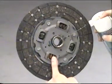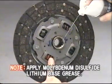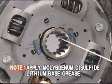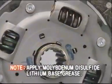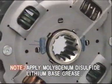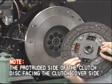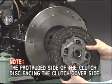After necessary treatments, install the clutch disc and the cover. Apply a coat of molybdenum disulfide lithium-based grease on the clutch disc splines. Be sure to set the clutch disc with its protruded side facing the clutch cover side.